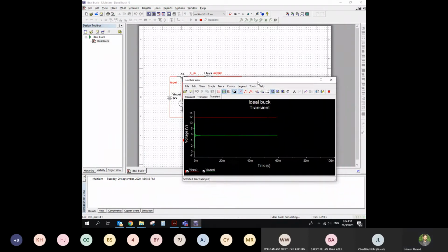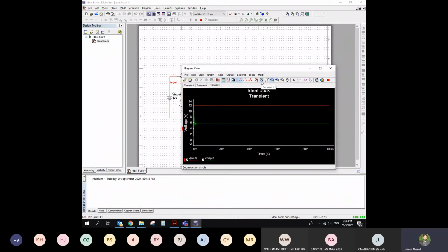Okay. So you're simulating it. You can see clearly this is the transient level. So this is our transient behavior of the inductor. Output is flat. In the transient level at the beginning, the output was quite high. Then there is oscillation and there is damping going on. So after the damping, at the steady state, it is settling down. This particular behavior depends a lot on the value of the inductor and capacitor, how much the overshoot is going to be and how long it will take to stabilize.